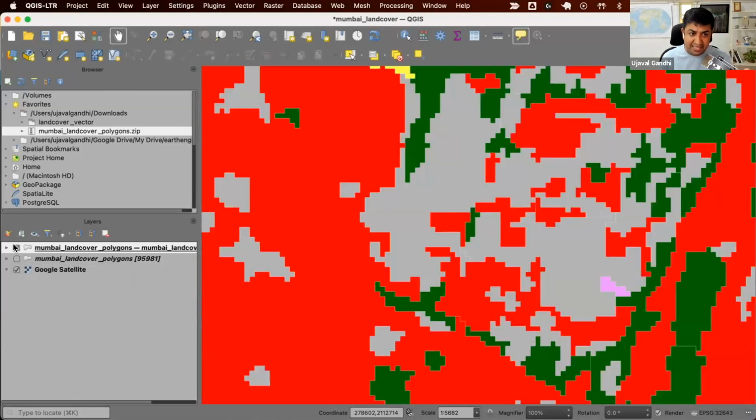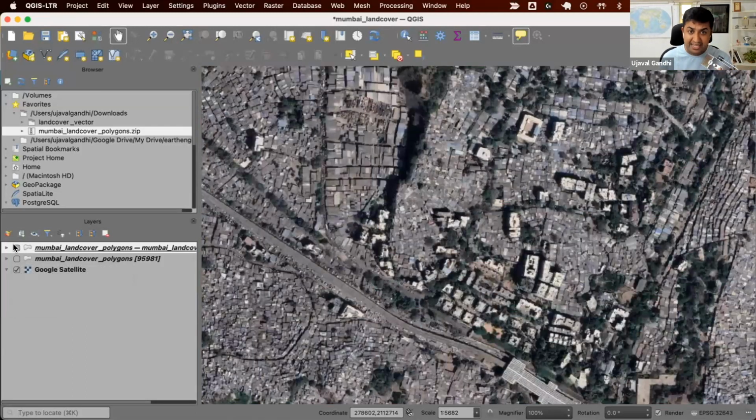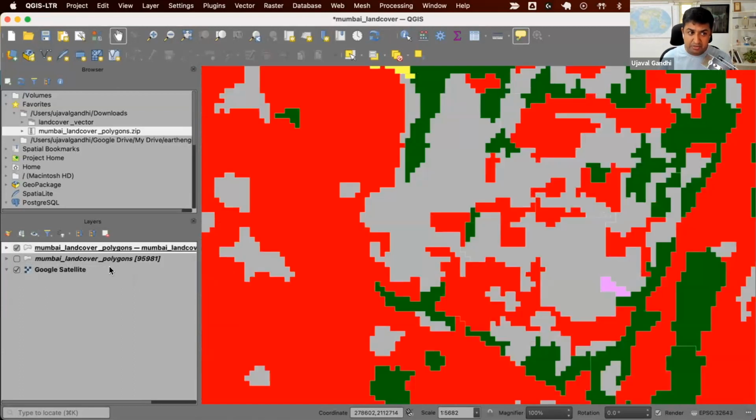And since this is a city area and most of the bare areas are actually urban, we may want to just replace all the values of the bare pixels with the urban values. So we'll take all the polygons which have been classified as bare with the value 60 and we'll make them urban, which is the class 50. So let's see how to do this in Mapshaper.